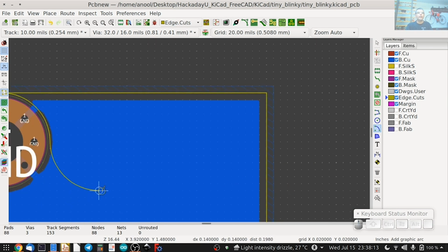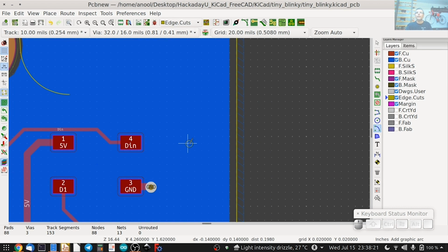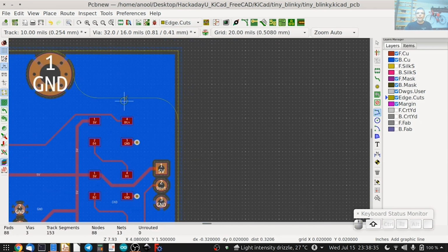And finally a third one over here. Start off here, go in the counterclockwise direction 90 degrees, click once, and then select the line tool and draw a segment from the end of this arc to the start point of this arc.